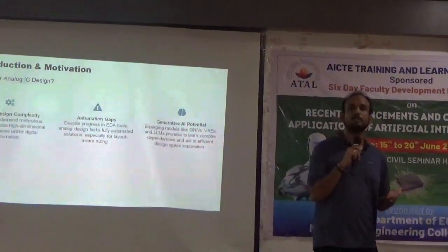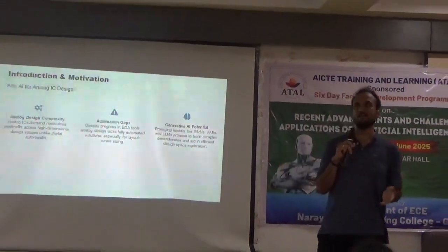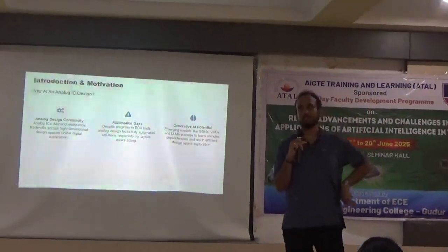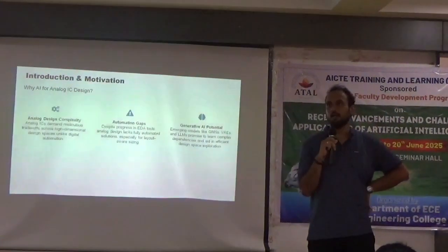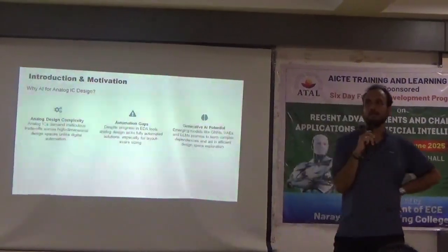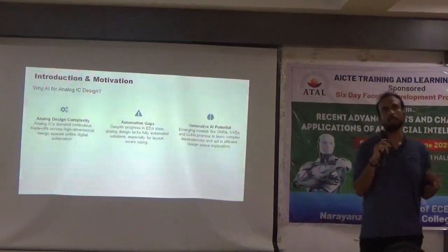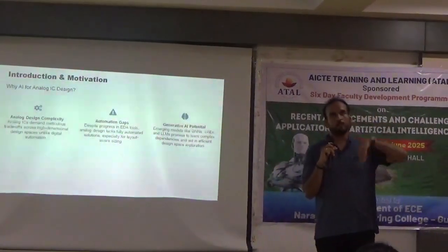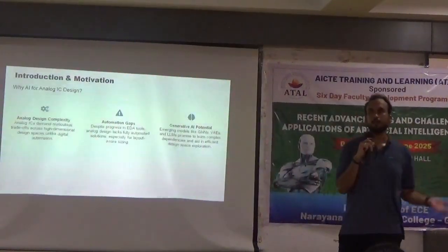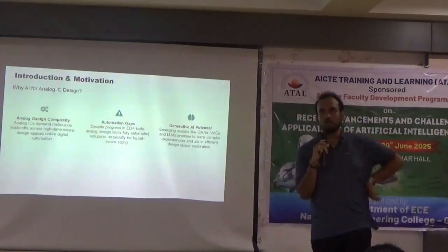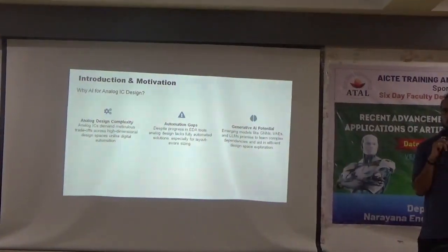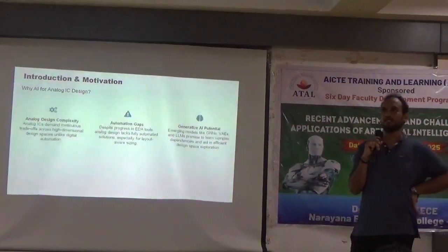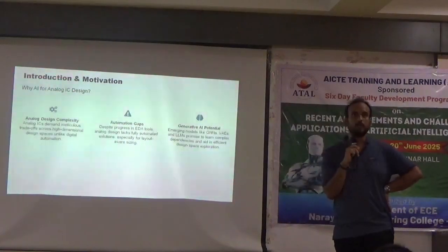We have one circuit, and it is very difficult in real time to optimize the circuit. You make a schematic, then you make a layout, and then you find that some parasitics come in the layout, and you do not optimize that. You have to go back to the schematic and retune the design. That is a big challenge. It's a very hectic job. So this is something where AI can play a role, where you can do the optimization